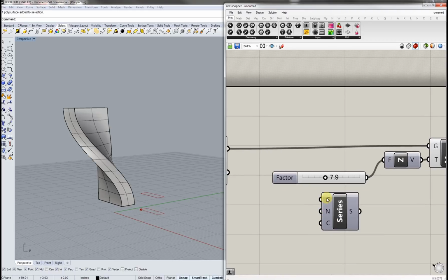So in Grasshopper, you need to justify a vector for this movement up. Our vector, obviously up, is Z. So if we type into Grasshopper Z, that's our vector up. And if we hover over these little plugs, geometry, our base geometry, which is the rectangle, and we plug it in there, we can see that our rectangle moved up.